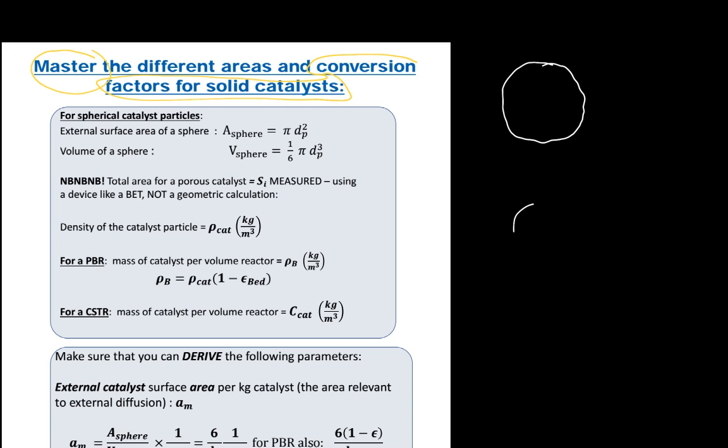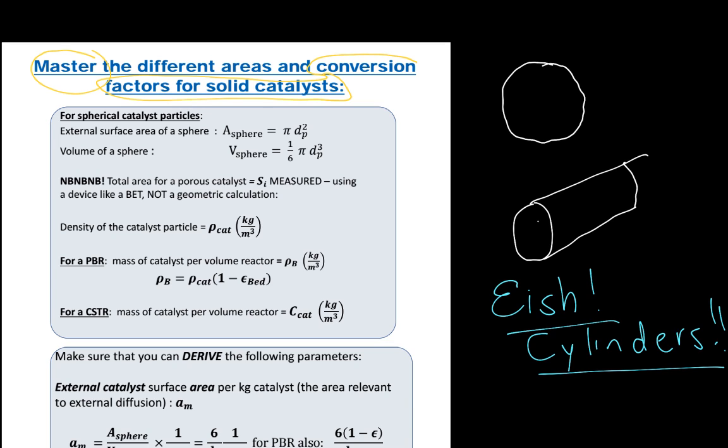It is important to note that you can actually have several other shapes of catalysts. You can have extrudates that look like little spheres. They can even have a little hole inside, a shape specifically designed to allow for better mass transfer. But as I mentioned, for our course, we are only going to focus on perfect spheres when we consider the geometry of our catalyst particles.